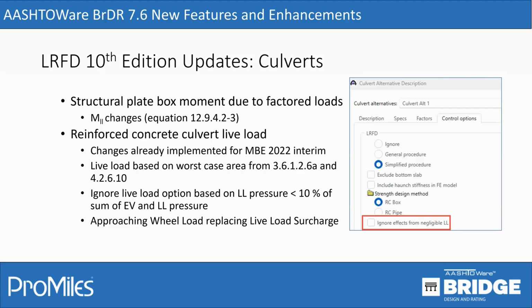There was a change in an equation for the moment due to live load for structural plate box. This computes the factored live load moment. So this equation was simplified, and there were a bunch of updates for reinforced concrete culvert live load. These updates essentially came from the MBE update for the 2022 interim and LRFR, and those updates were carried over to the LRFD spec now.